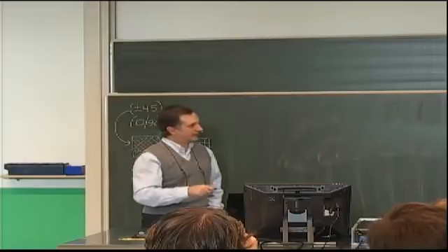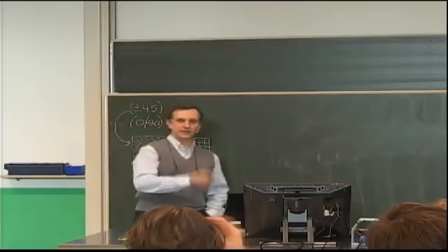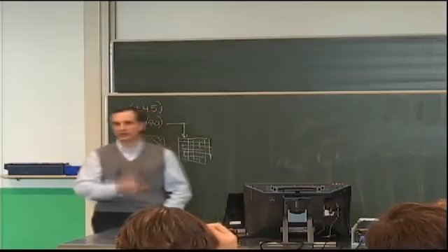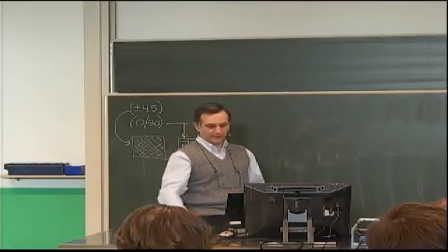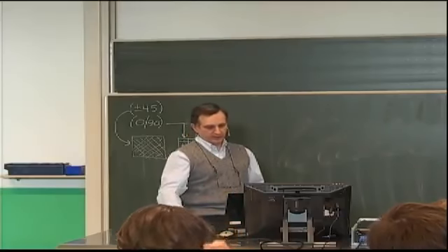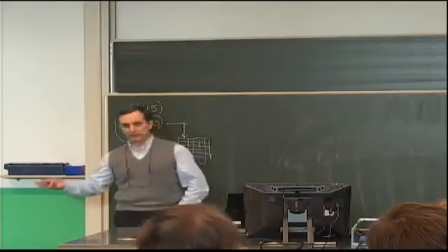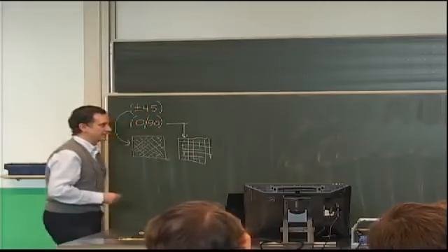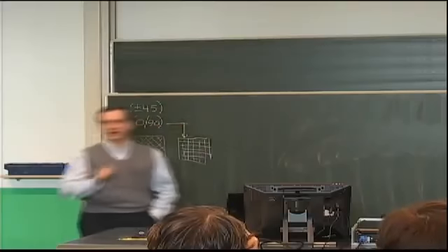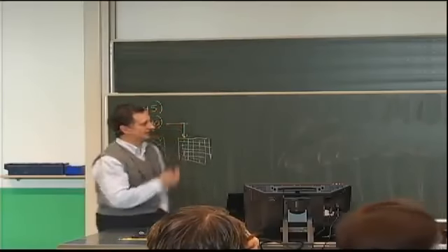So the final aspects of this design would actually require determination of these stresses and the tendency to create a delamination or failure of the matrix in between the stiffener and the skin. But the purpose of this exercise was more to see a complete solution of the governing equations more than anything else, which we did here. But as I'm emphasizing, you need to address also the bending moment and the interlaminar stress issue to complete that